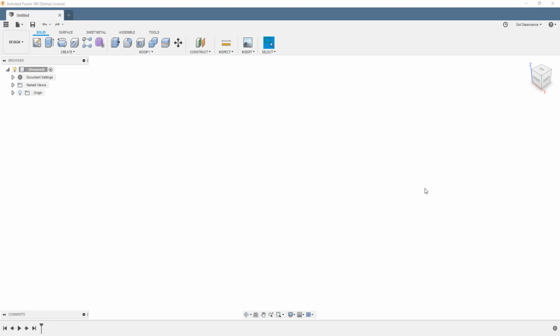With the release this past year of KiCad 5.0, they now support IGES files directly, so you could just export out of your good old CAD package right into an IGES file or a STEP file, and you can bring it basically into KiCad, and you can use that for your 3D shapes.